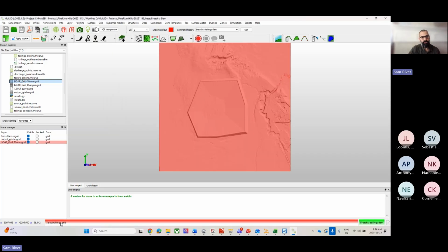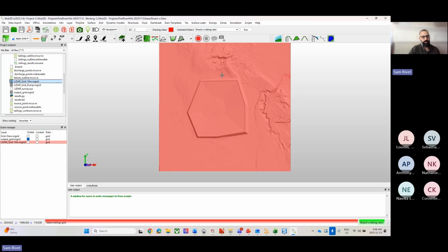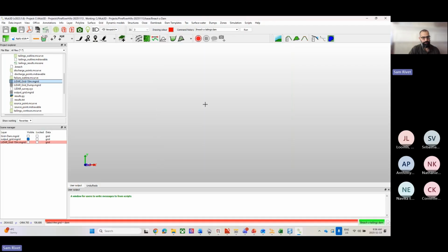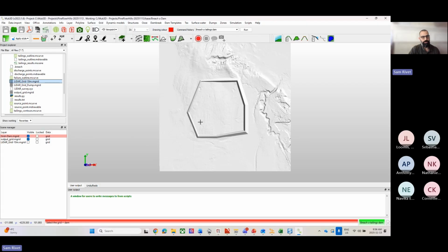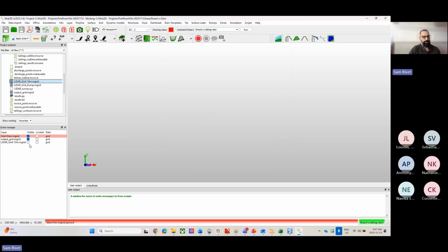Here it's asking you for your tailings grid. Your tailings grid is your output grid. It's your grid with the tailings merged in. So I'm going to turn the visibility of those other two surfaces off and choose my output grid. It's asking me for grid plus dam, so original ground surface plus the dam. This is how it's distinguishing between what it wants to consider as TSF material that's being contained within versus the embankment structure itself. And then it wants the original ground surface.